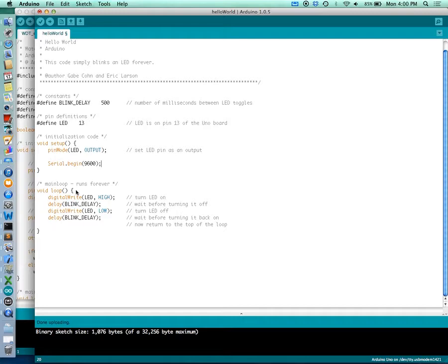Okay, so now every single time that I've blinked the LED, I'm just going to do serial.print, and then I'm going to say LED blinked, like that. Actually, you know what I should do here? End line. That would be nice. I'm going to save. I'm going to upload this.